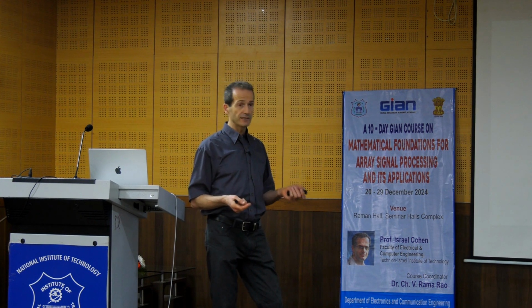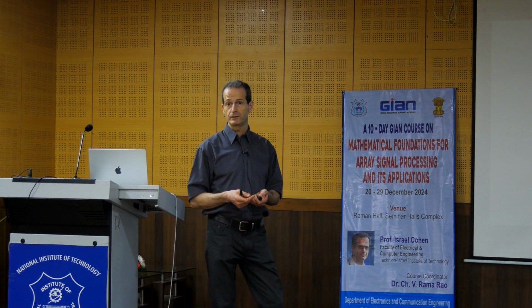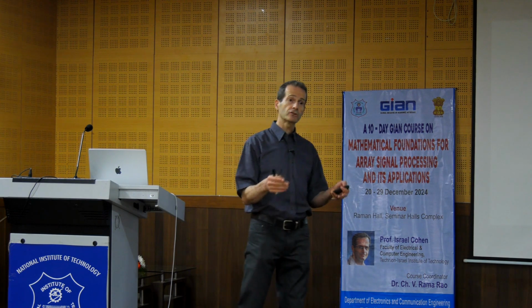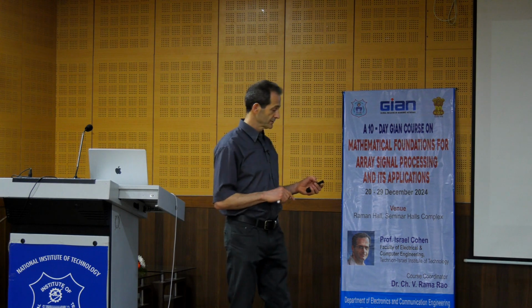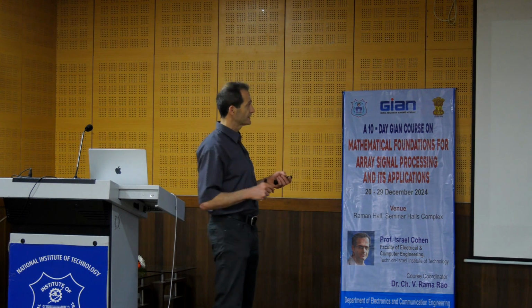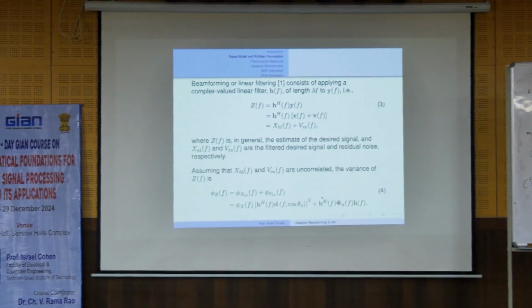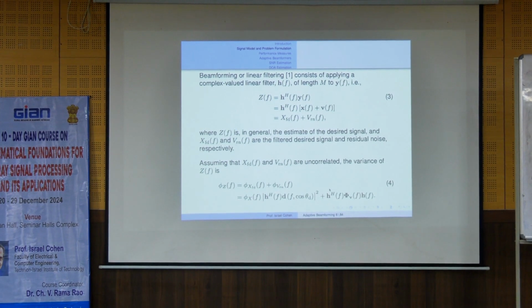So we can find an optimal adaptive filter, beamformer, that adapts to the actual statistics of the desired signal and the noise sources. That's why if we use this information, we call it adaptive beamformer. But it's a beamformer because we work with directions. This is the only difference, because we work with directions instead of relative transfer functions.